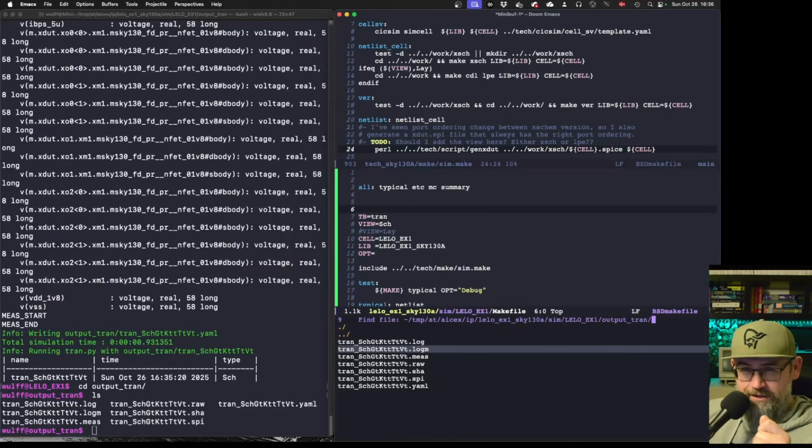it's a very good idea to split up simulations into an actual simulation and parameter extraction, because quite often when we're running analog simulations they take a lot of time. For example, let's say it takes 24 hours to run the simulation. What you don't want then is that you've forgotten to add what's called a measurement of something.